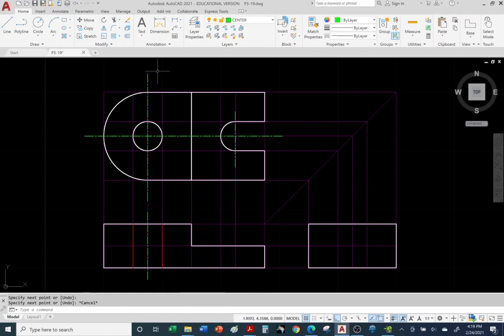You do not want to use one long green center line going from one view to another. It has to be two separate center lines. That's one of the rules about creating your orthographic views. You cannot extend a green center line from one view to another just to go fast, or to use fewer steps. Okay, so I'm not going to complete the 3 views,